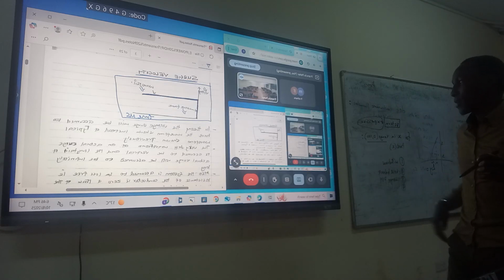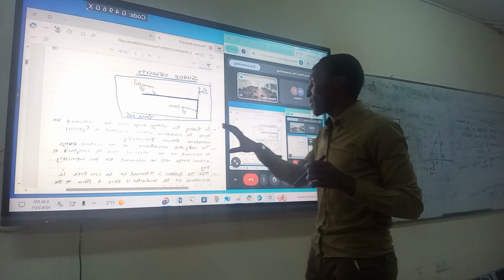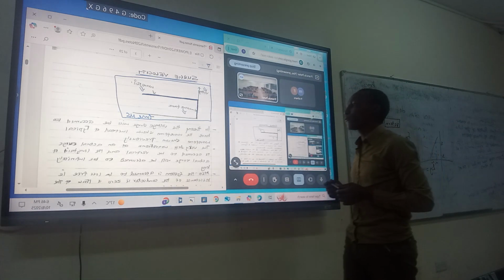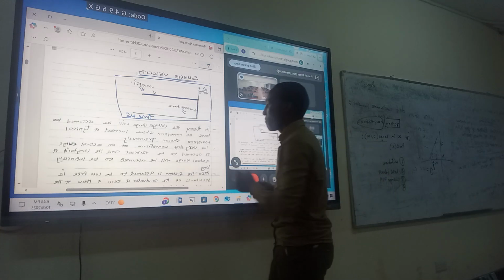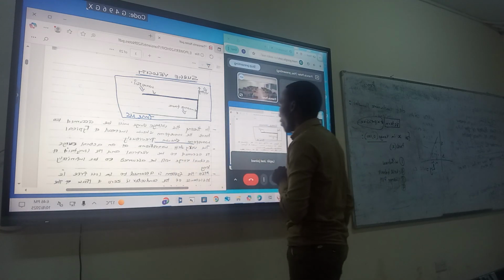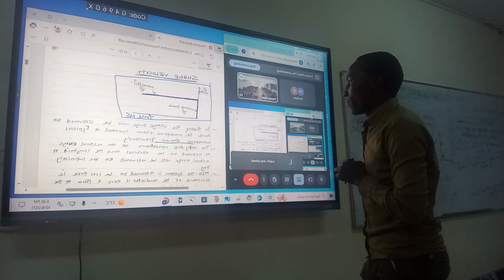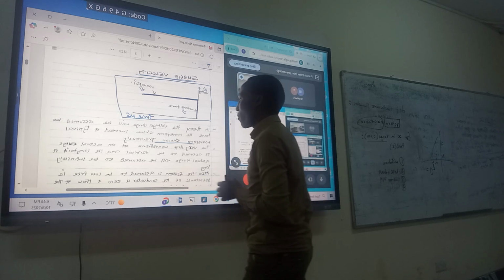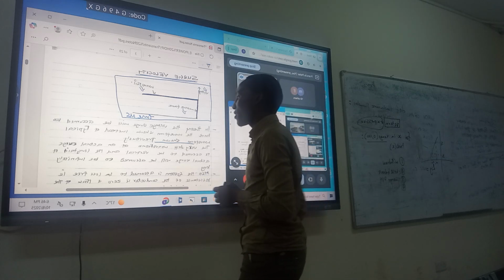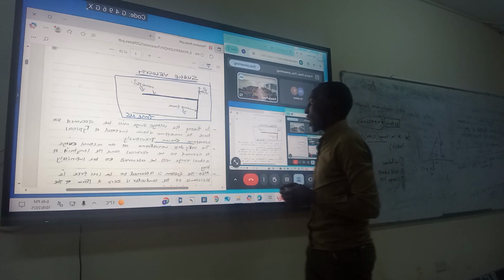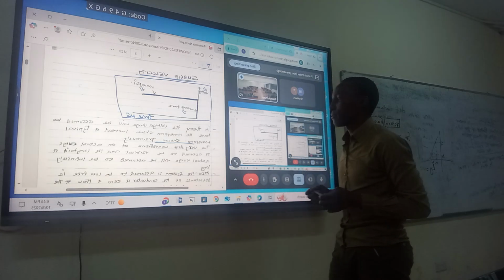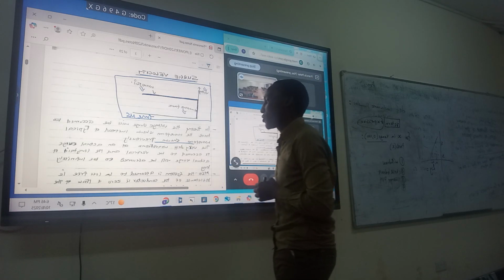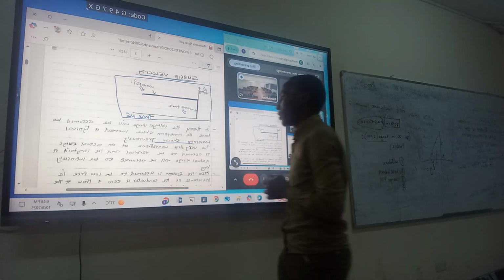So we are saying that in theory the voltage surge will be assumed to have the waveform shown, instead of the typical waveform shown previously. That means the wavefront of an actual surge is assumed to be vertical, and the long tail of the actual surge is assumed to be infinitely long.